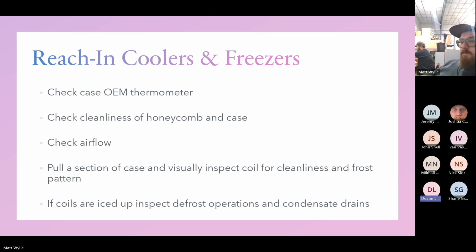The center mount coils, I'm sure you guys have all probably seen those. I remember when I was in Reno, I had a guy go in to de-ice a freezer. He told me like 20 minutes later he was all done, and I was like, no way, there's no way you're all done. And he's like, yeah, I got all the ice off. So I go in there, and he's like, see, I'm all done. And yeah, he got all the ice off the outside, and I shine my flashlight up in the inside, and it looked like a freaking iceberg in the Antarctic Ocean up there. I'm like, no, you got to turn it off, take the guards off, take the blades off, and you got to hose out the inside too.